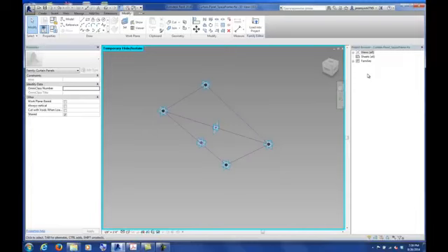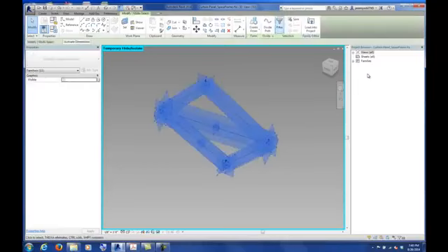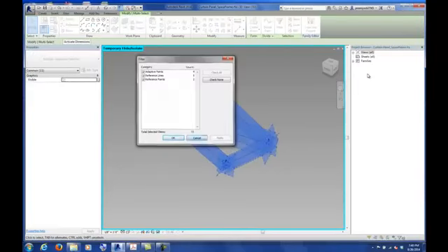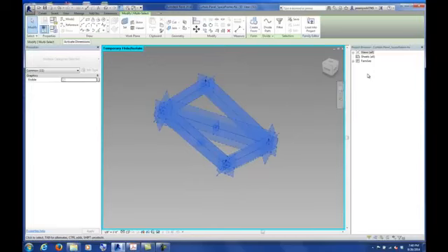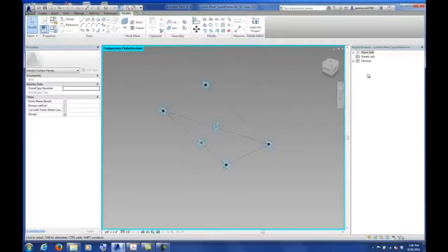Well, I was trying to do the thing for the spheres, like labeling them. Uh-huh. So I haven't got past labeling them. Okay. But yeah, we're both there. Okay, so let's not worry about the labeling part. That's something we can add in after these steps. So you guys can actually select everything like I just did in your curtain panel and go to filter up on the top right. And then I unchecked generic models. Then go to your eyeglasses and then hit isolate element. So basically everyone should just have their reference planes and then these points.